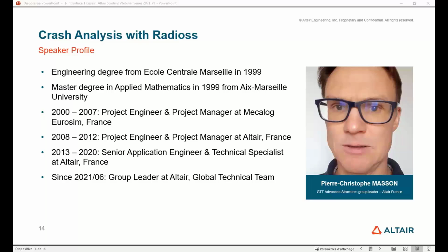Yes, I guess we can try to use that kind of approach, but this is a complex simulation here, to have the thermal effects also due to the friction, and this is possible through the contact interface in Radioss to generate heat through friction. SPH, I guess, is maybe the best approach to have the mix of the different materials expected during the welding.